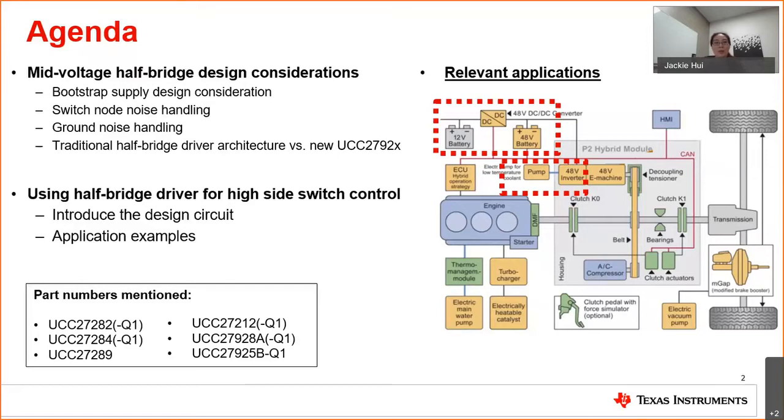In the second portion of this presentation, I will introduce an application circuit that can transform the half-bridge driver for use as a high-side driver with 100% duty cycle. You can find this in applications such as a battery disconnect or a DC circuit breaker.